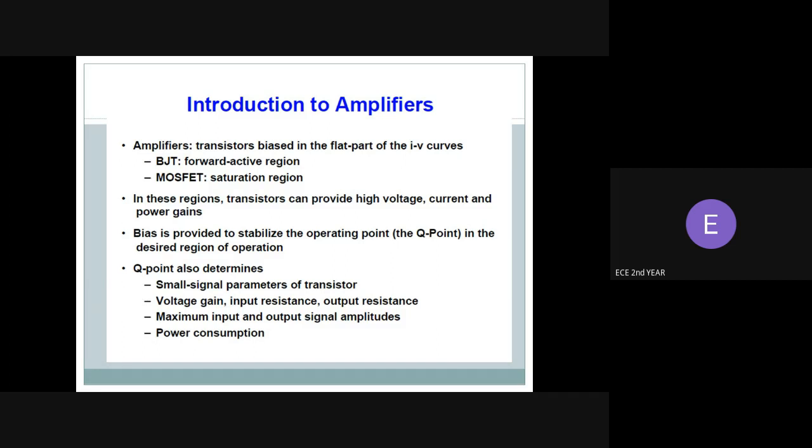As its name suggests, in common base, or grounded base configuration, the base connection is common to both input and output signal. The input signal is applied between the transistor's base and the emitter terminal, while the corresponding output signal is taken from between the base and collector terminal as shown. The base terminal is grounded or can be connected to some fixed reference voltage point.